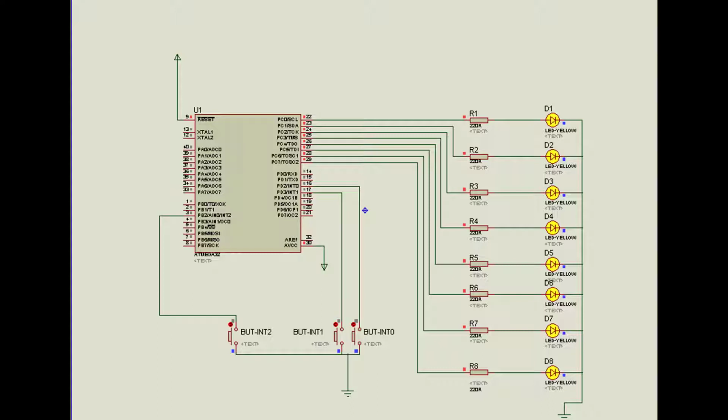As you see, after running the simulator, D1 is blinking quickly because D1 is connected to timer 0. Timer 0 maximum is 255. So that's why every 255 it will change state. For D2, timer 1 is 16-bit, so it will take longer time to reach its maximum. That's why we see D1 is blinking faster than D2.